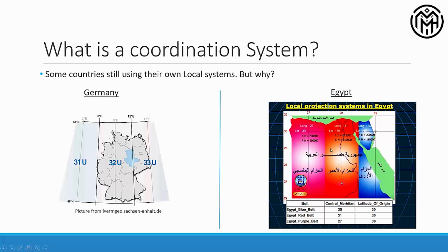So this is the origin for the different three coordinate systems, but this origin is not 0 and 0. They also assumed a false easting and false northing at the same time. Why? You already know the answer: to avoid any negative values if they moved down or to the left side. So they assumed a bigger number here according to the distance, and they decided to do this to avoid any negative values.